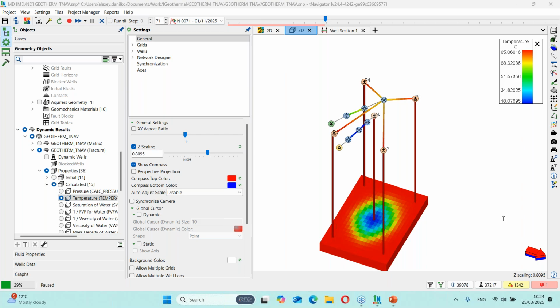We know how much fluid we're producing, and we know what kind of correlation we have for the pipeline. So we know the performance of the pipe, the VFP performance for the pipeline or the well, and based on that we calculate the pressure losses along the pipeline. We don't do it separately. This is one system of equations which is solved on every calculation time step. But we do support this functionality if you want to make an additional one-time-step nodal analysis for the pipelines or for the wells. So it's also supported.